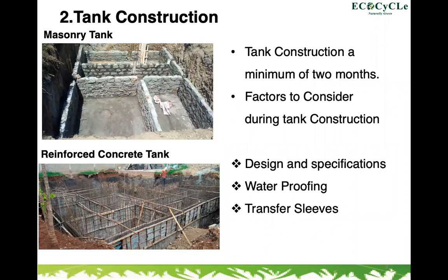And depending on the soil type, those are some of the decisions that also can influence whether you will do a masonry or a reinforced concrete, in addition to whether the top slab will be used to carry loads, e.g. like parking. So this bit requires the involvement of a competent civil and structural engineer working together with the builder's contractor, following our tank schematic drawing to make sure the final installation and the complete system will work efficiently.